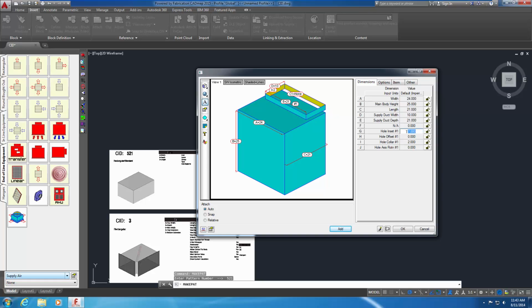Observe that the hole moved so far that it overhangs the end of the pattern. You can enter several different values and redraw to observe how the hole moves on the pattern. This enables you to understand what geometry is controlled by the dimension. Change 7 to -6 and redraw the item. The hole now goes to the front left in the negative X direction.